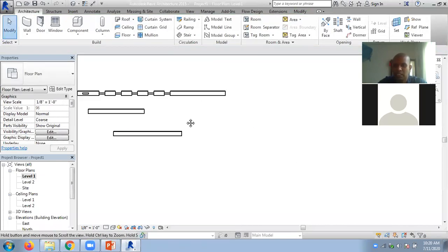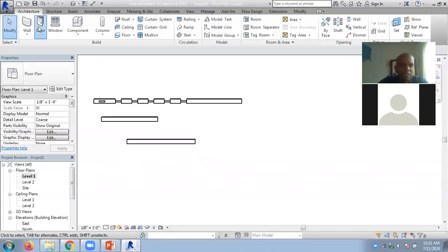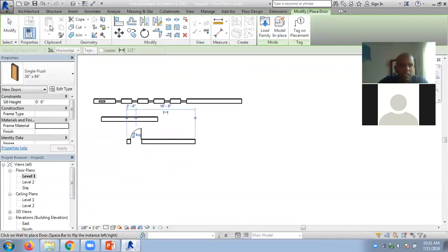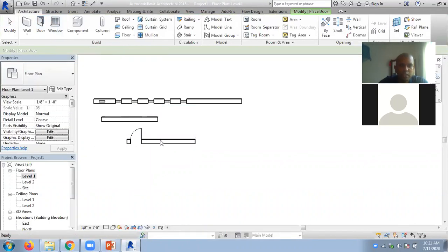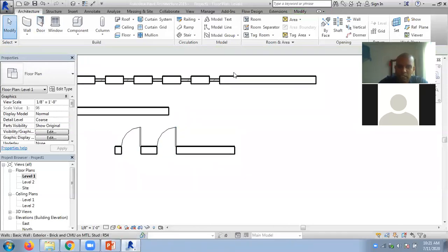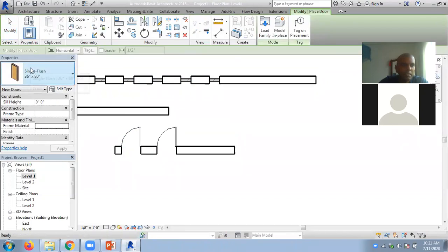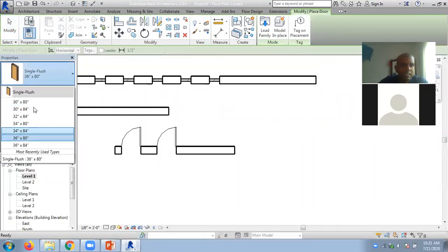Now this matters when you have a big drawing. Say I have a door here. I have another door type. Now if you want to create this door here or this door here, one way is you can come here and get it from here. You can look at the name here. The name is 3684, and come here and select the 3684 and do it.